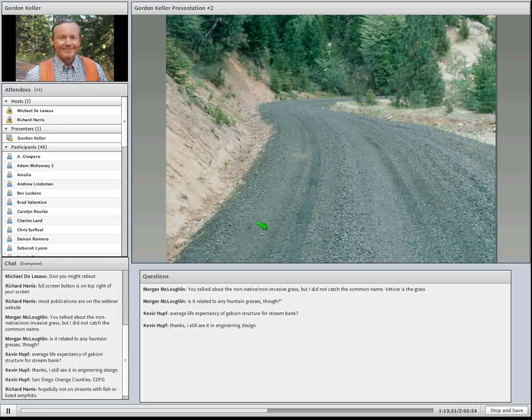The aggregate, crushed aggregate, gravel, pit run rock, they're probably the most common type of improvement you see on low volume roads because it's relatively inexpensive. If you can find material close by, you can keep the cost down, and you both provide structural support and also remove some of the dust problem and mud problem once you put down aggregate.